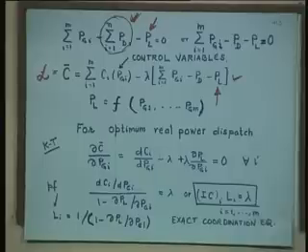So I hope you have understood the difference between necessary conditions and sufficient conditions. Your earlier teachers in optimal control or in optimization might have explained what is a necessary condition and what is a sufficient condition. So these Kuhn-Tucker conditions are necessary conditions for the optimum to exist. So for optimal real power dispatch, you differentiate the Lagrangian with respect to the control variable.